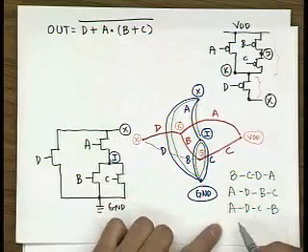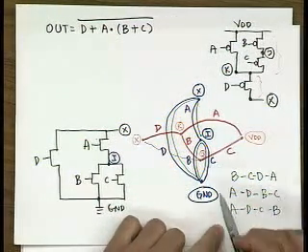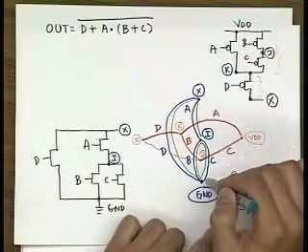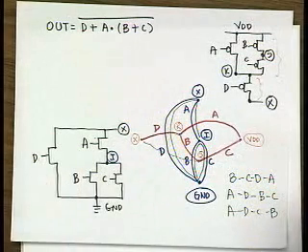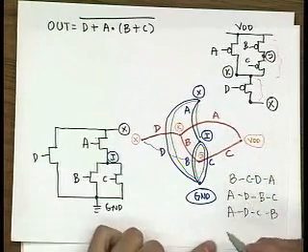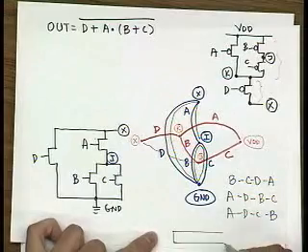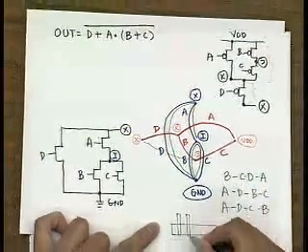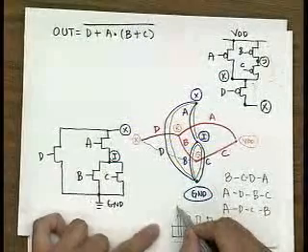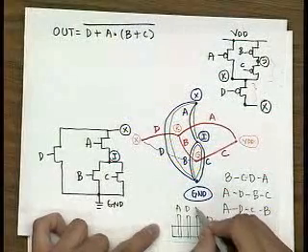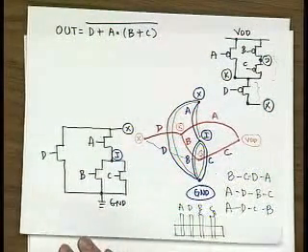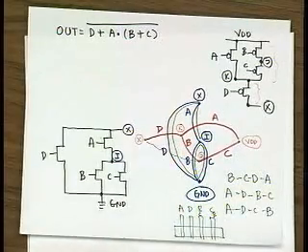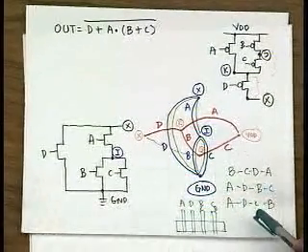Now, what this tells you is that the sequence of these edges actually tells you the arrangement of all these gate signals for your vertical diffusion strips. In this case, you would have, for example, an implementation of a NAND pull-down network, and then you have a certain way in which you order all these diffusions. A, D, B, C, or you can have C and B. So you can basically play around with this arrangement until you find the best solution for the highest layout density.